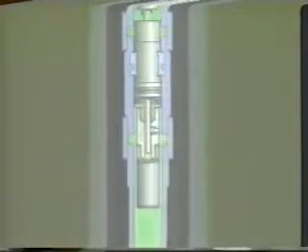In order to unlock and retrieve a tubing lock, it is necessary to equalize any pressure that might be held beneath the lock and its attachments. An equalizing sub is normally run between the tubing lock and the subsurface control for this purpose. The equalizing valve is held in a closed position by a spring and protrudes slightly into the bore of the body. To equalize the pressure beneath the lock mandrel, a prong is run attached to the pulling tools. The prong is run through the bore of the lock mandrel and pushes the valve open. Once the pressure has been equalized, the lock may be unlocked and retrieved.